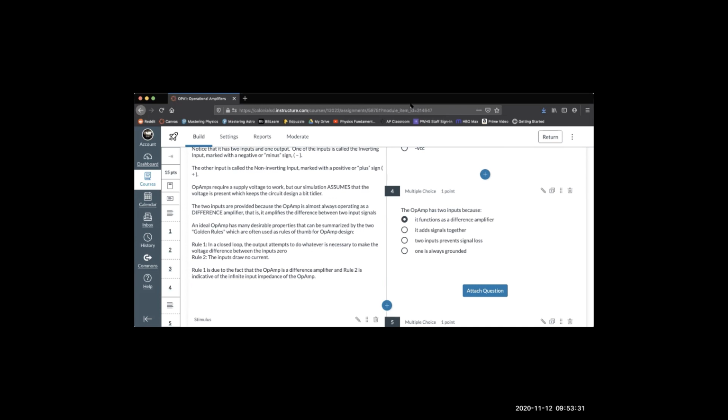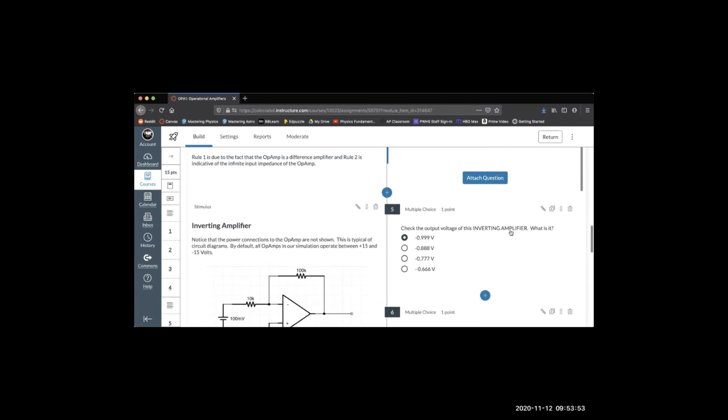We have 2 inputs into the amplifier, and if those inputs are the same, the amplifier doesn't amplify anything because what it amplifies is the difference between 2 signals. And in that transistor circuit, we shifted one of the signals by 180 degrees so that they would be completely different one from the other, creating a difference.